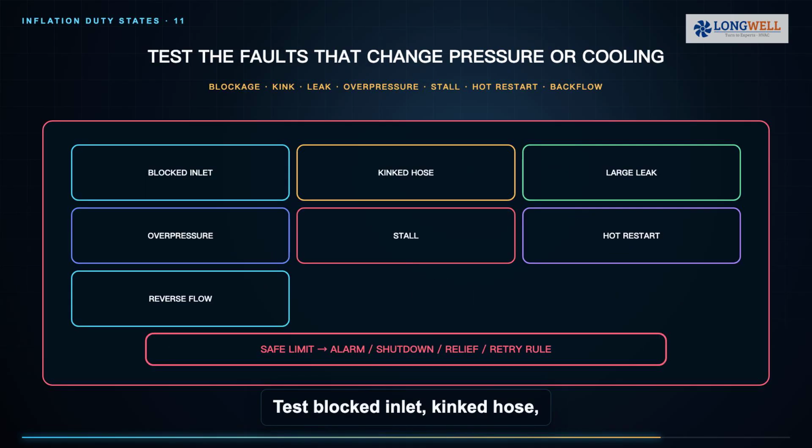Test blocked inlet, kinked hose, large leak, overpressure, stall, hot restart and reverse flow. Define safe limits, alarm or shutdown behavior, pressure relief where required and retry rules. Validate voltage extremes, repeated cycles, high and low temperature, acoustic change in life.